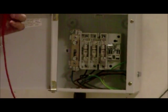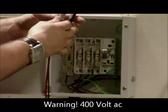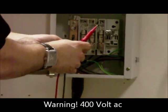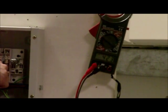So now this is where we're going to be measuring the 400 volt. You need to be extra vigilant for this, okay? So you take your time, just put your neutral lead on first, go between the two protected devices. You'll see that we're measuring underneath. Remember, the top terminals will be isolated because they are isolated mechanically.